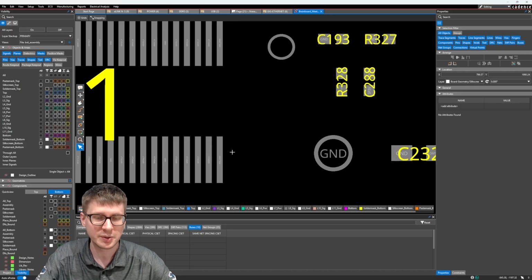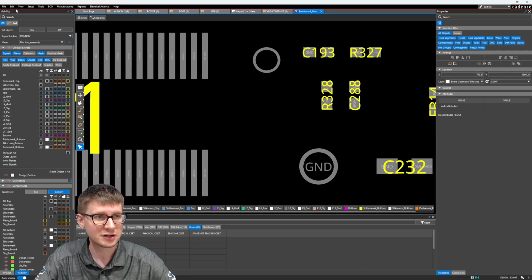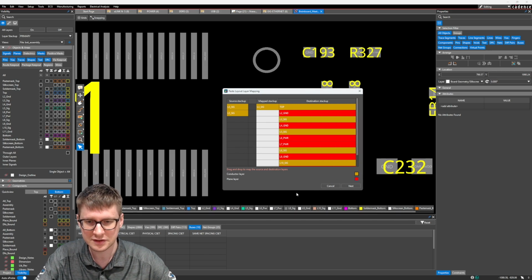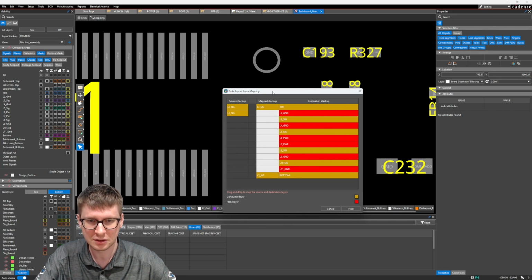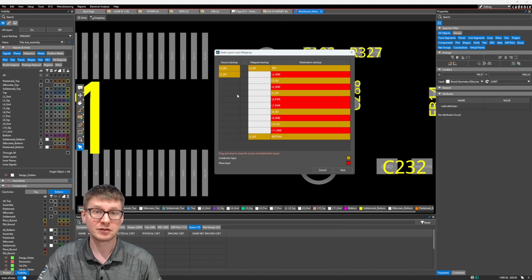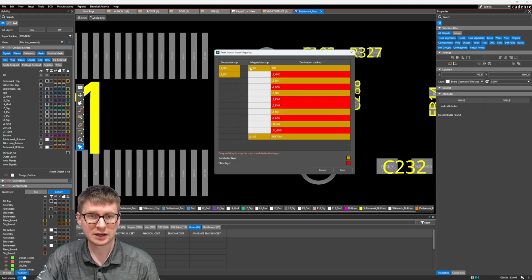And let's go ahead and paste this layout. We snapped to this first pin here, but maybe we want to paste it on a different layer. So let's look at how that would look. Edit, paste layout. We get this nice set of options here where we can choose where to paste that information. So our layer 3 signal copper, for example, we can now put on layer 8, and what was on layer 5, we can put that on the top layer. Again, just as an example.